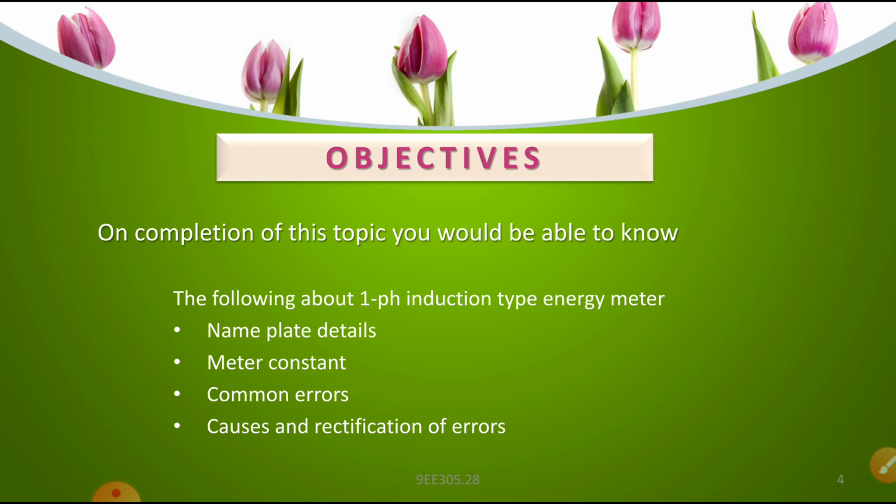If you take a motor, you have to observe and check the rated voltage, the rated current, the rated speed. Everything you have to observe. Dear students, anywhere you are going to operate any appliance, first go and check the nameplate details, whether it is connected in star or delta connection, what is the full load torque, the starting torque, the full load current. Everything you should keep in mind before handling that machine.